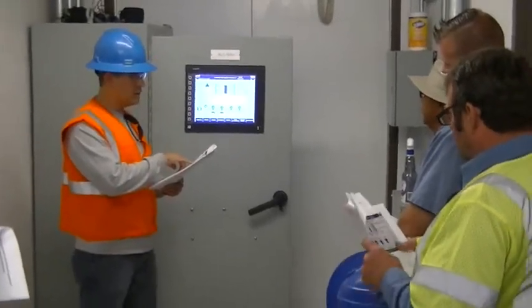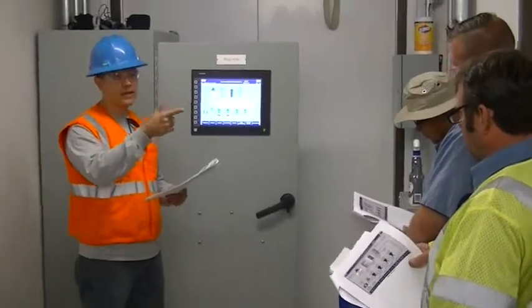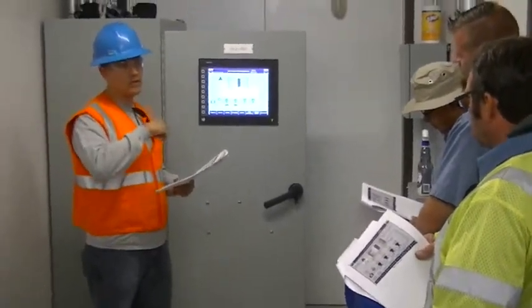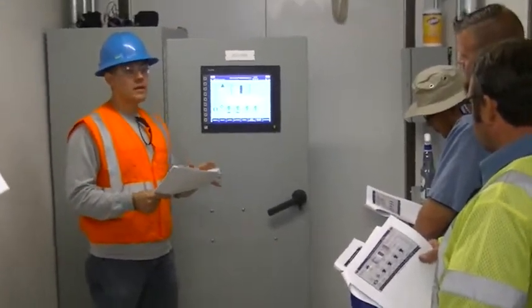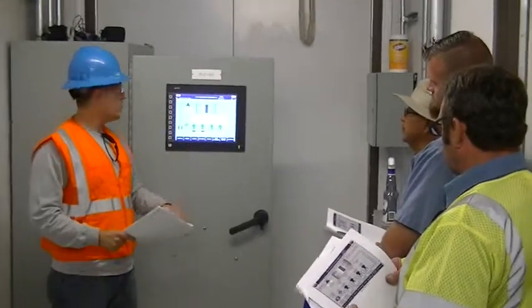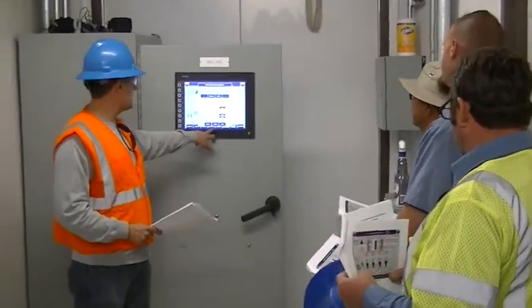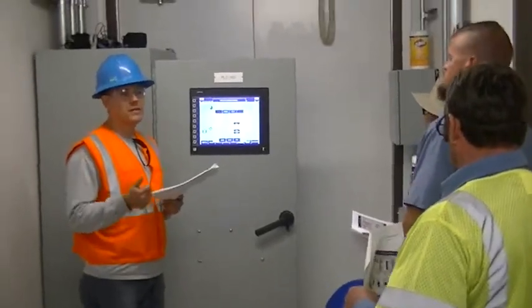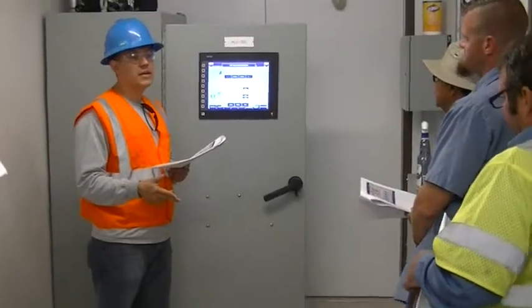signal. You have a fault, which is actually a physical input from the motor that it's faulted, or the VFD cabinet that it's faulted, and that'll show up there. That'll lock you out. That fault will lock in. So even if the signal goes away, you have to reset it. The reset will be right here, this button. That'll reset basically faults, low flow conditions, or PSHLs to get it out of that.